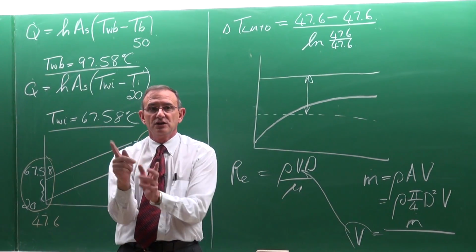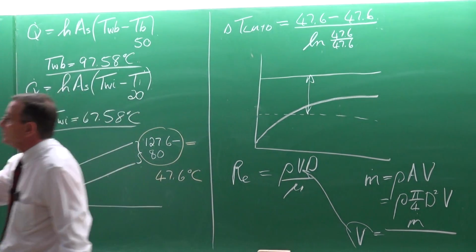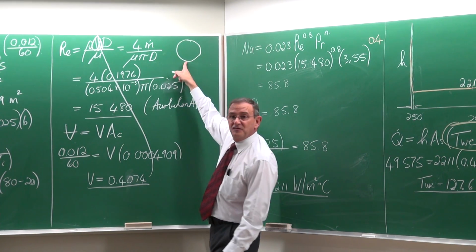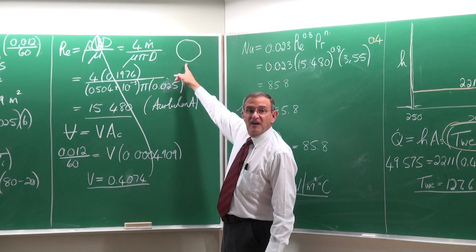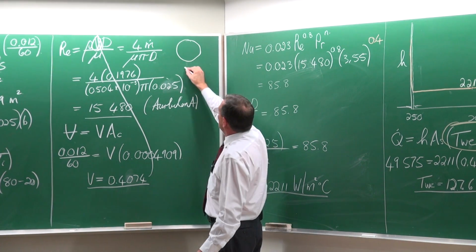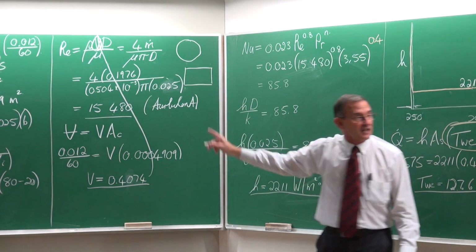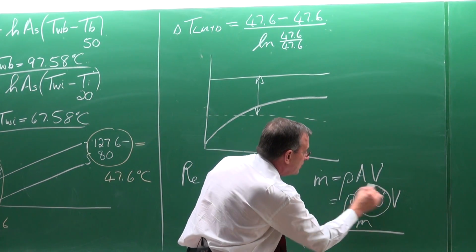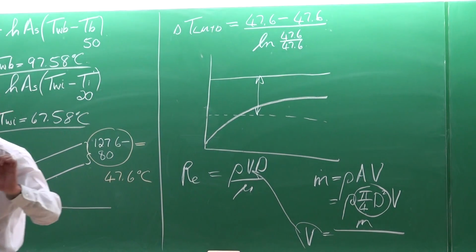So we've done that derivation. However, remember, and that is now where I say this is important, ladies and gentlemen, you have to listen well. Previously, when we derived this equation, I put this next to it. It is valid for a circular tube, but it is not valid if you've got a cross-sectional area like that, because this was based on the circular tube.